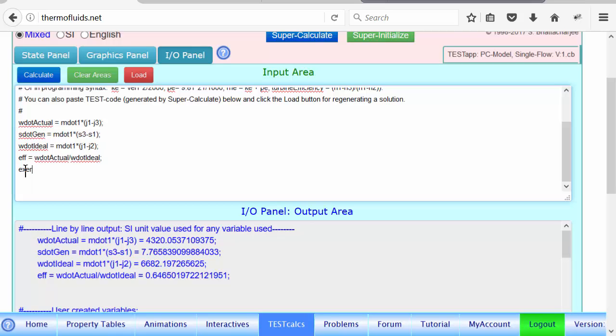Suppose we write down the exergy difference, for lack of a better term, m dot 1 star, psi 1 is coming in and psi 3 is what is going out. So what is that quantity, 6635, that we just calculated? That says that the useful energy that comes in minus that goes out, the difference, is this. In other words, the turbine could have produced 6635 if it were a reversible, an ideal turbine, an engineer's dream.